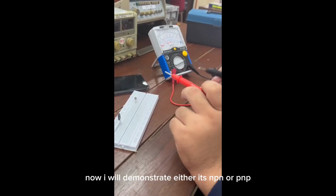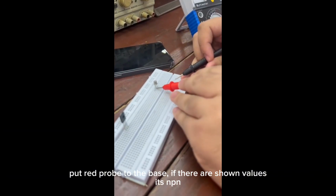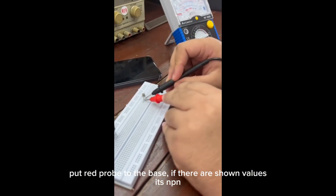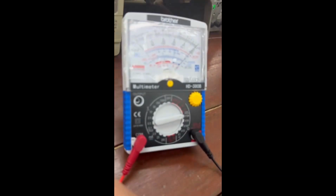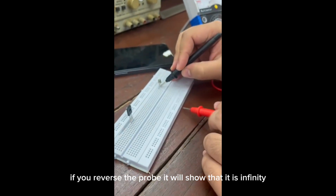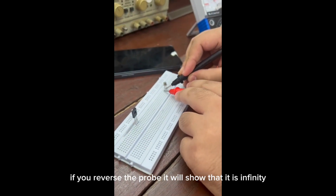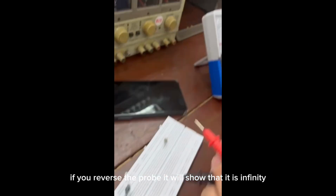I will demonstrate whether it's NPN or PNP. Put red probe to the base. If it shows a value, it is NPN. And if you reverse the probe, it will show infinity.